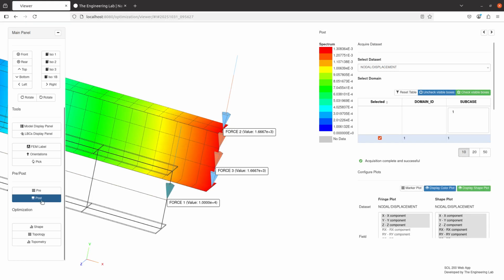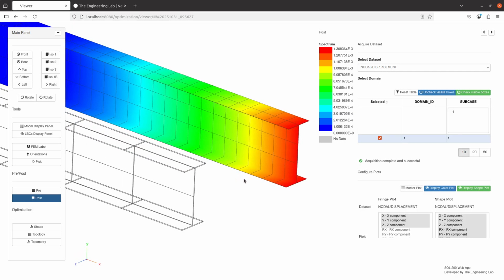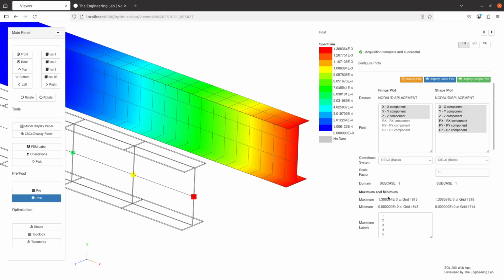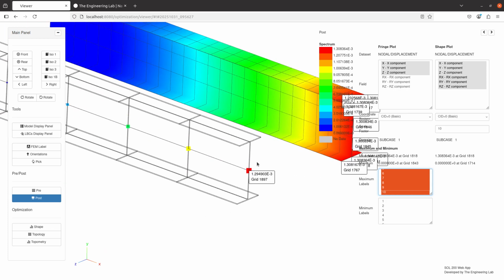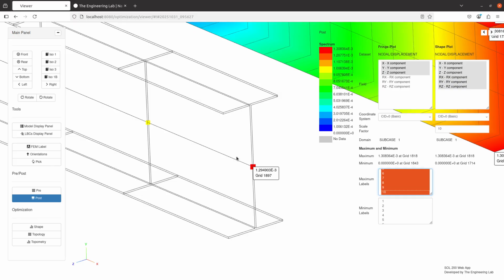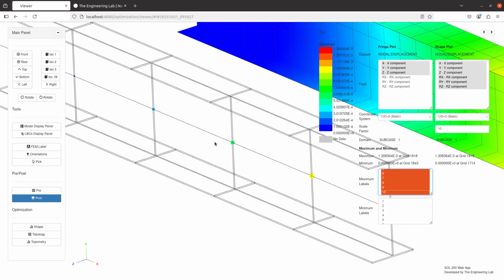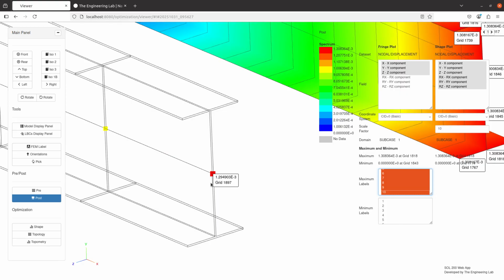Okay, we've gone ahead and performed a statics analysis on this loading scenario, and here are the deformations. Now, there's one problem when we look at the deformations. So here, let me go ahead and plot the maximum deformations. For this beam, it's really easy to know what the maximum displacement is for the beam. Here we see the maximum deflection is reported along the beam elements, which represent the shear axes of the beam. So here we know we have a deflection of about 0.00129 meters.